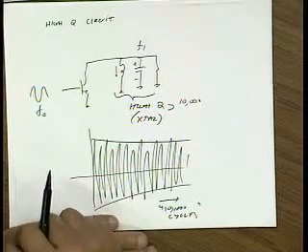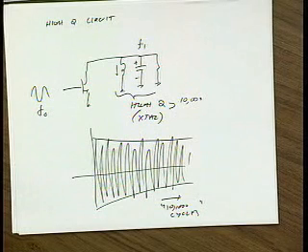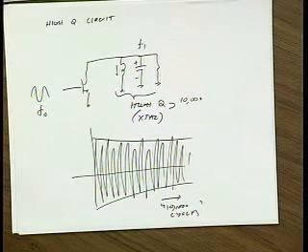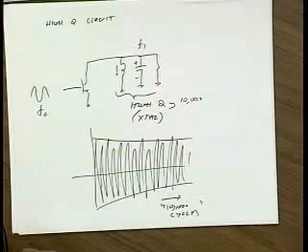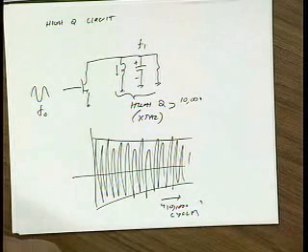Okay, any questions? That makes sense? Okay, I think I have a question back here. So what if you have multiple tones in your system and they're not integer multiples of the other frequency? What's the period? Well, you still get the beat frequency, right? No, 1 megahertz, 3 megahertz, 5 megahertz. Yeah, it basically never goes into true periodic steady state. It goes into quasi-periodic steady state. And there is another analysis inside Spectre to handle those kinds of circuits. Okay, good, very good question.